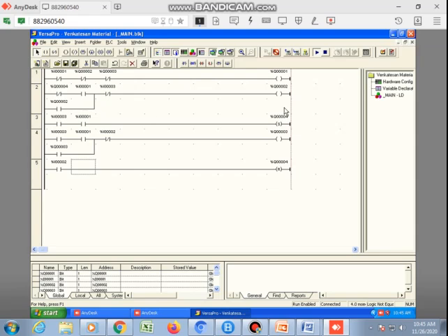That is, I should start the robo arm towards forward direction to pick the material when the proximity sensor is sensed. By that time the electromagnetic switch is to be low, so I am going for an interlock condition. When I am satisfying these two conditions, I will start moving towards forward, towards my material.